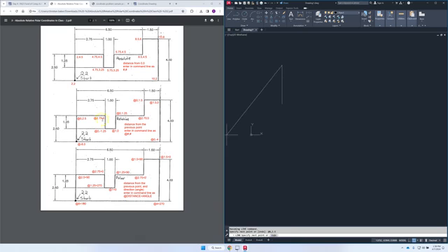Then you could type in the next change. So we go to the right in the x value, 2.75. So I would type in @ 2.75 in the x, 0 in the y. So relative is acting like the point you were at was 0, 0, and the change is what you actually type in. You could use either one of those methods, absolute or relative, to draw this entire shape.